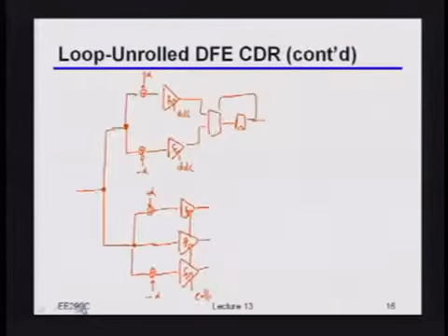Okay? So just to make sure it's clear, as we said, the 0 threshold is basically dealing with a clock pattern, right? So that means you have something like 101 or 010. That would be a clock pattern. For this upper one, where I've shifted the threshold to plus alpha, what kind of transition is that? 110.